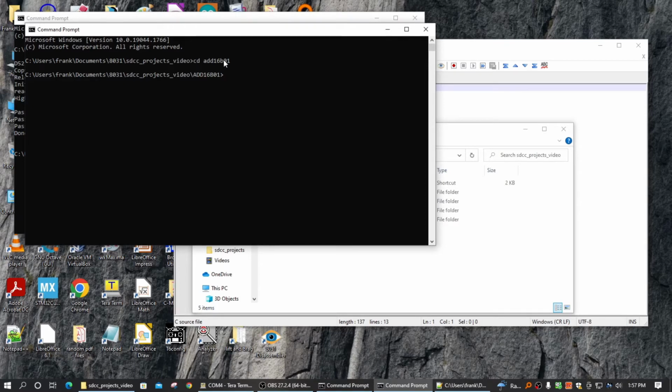So we're going to run the compiler again in a similar way as we did before, SDCC, and we want to get the code location at 800 and the data location at 30.